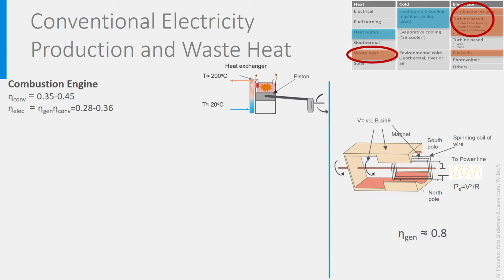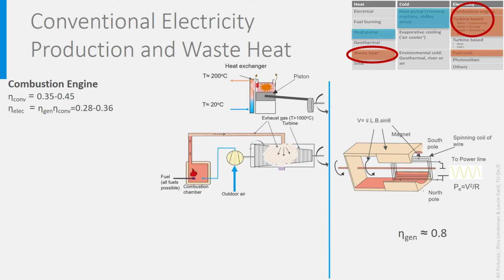Let's look now at turbine technology. The basic idea here is to connect a turbine to the coil's rotor. By injecting high-pressure gas in the turbine and to expand it towards lower pressure, the gas will impact the blades of the turbine with a high velocity, making it rotate. How do we get this high-pressure gas? Well, here too, that will be by burning a fuel in a boiler, generally gas, but also coal, liquid fuels, biofuels or hydrogen. But this time, by making use of the exhaust gases.